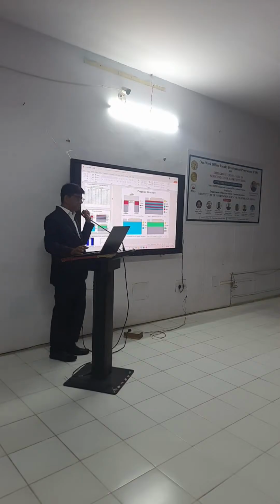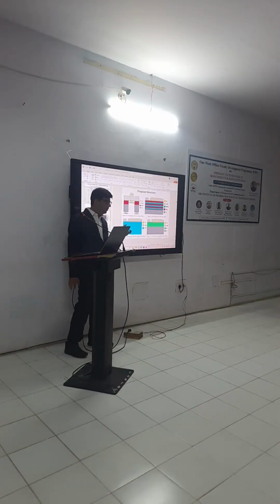So first we have to decide the thickness of all these. Let's suppose the thickness of the PET substrate is 100 micron. Then 150 nanometer is my bottom electrode thickness, and then I have a 2 micron thickness of my ZnO layer, and 150 nanometer is my top electrode layer thickness.